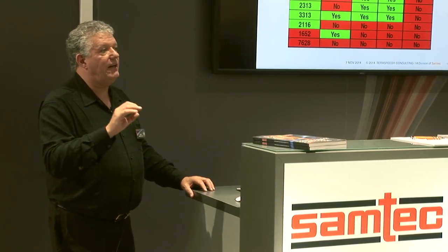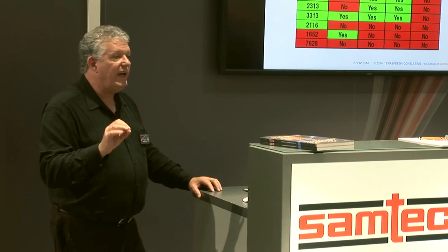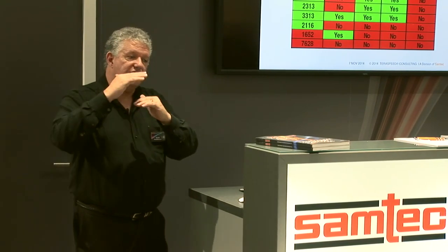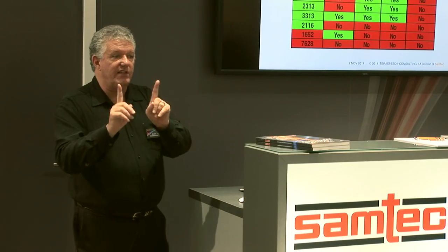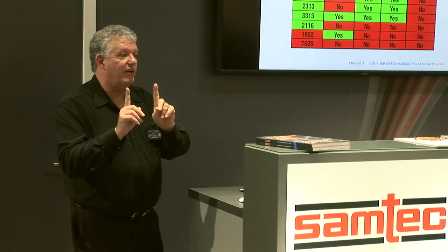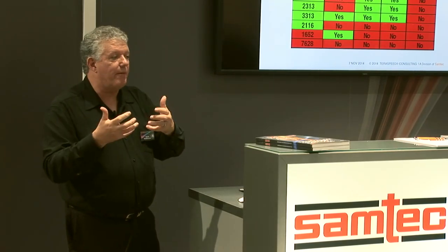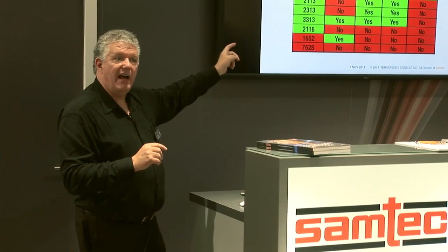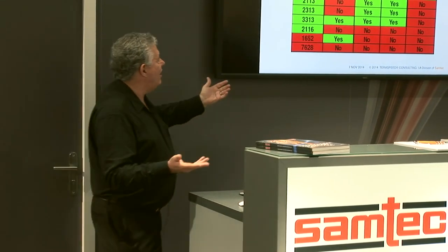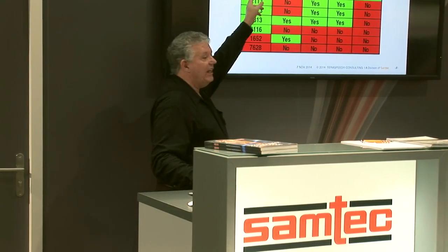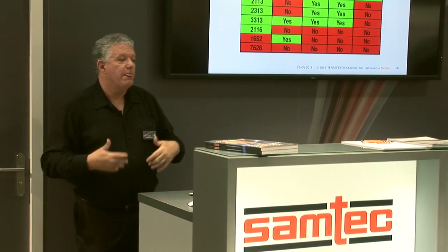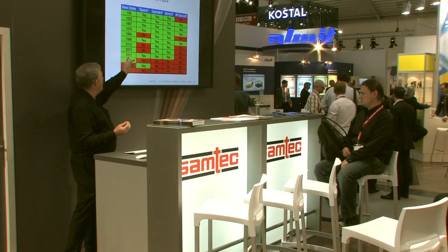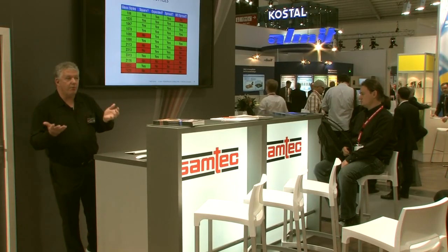So for high-speed, high-performance engineering, we have to actually not just specify the trace width, the dielectric stack-ups, the trace separations for differential pairs, and the dielectric properties, but we also have to specify the actual fiberglass that's being used. So we would call out for example, a 1086 core that is 5 mils thick. Or we would call out a 3313 prepreg in a layer.